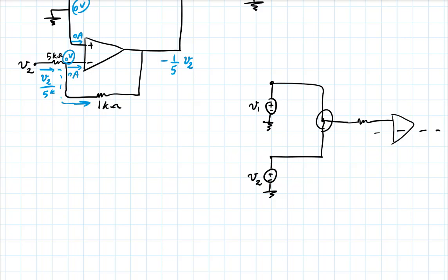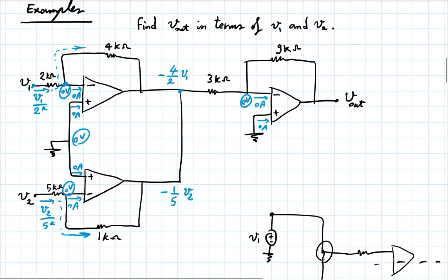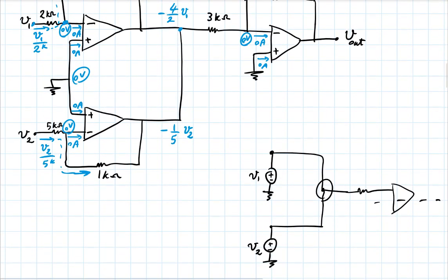Now this you see readily, because if I have a 1.5 volt battery and a 9 volt battery, and I ground the negative side of both of them and connect the other sides, you will say, well, I had better use a wire that has a very high resistance, right? Otherwise, I'm putting a huge conflict between the two batteries. If it's really a good wire there, it means I have infinite current. Voltage difference over 0 resistance, infinite current. Not good. Okay? What you see up here in this op-amp circuit is not very different.